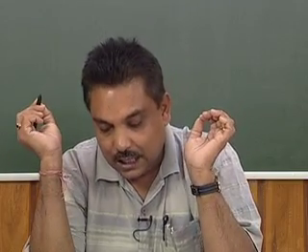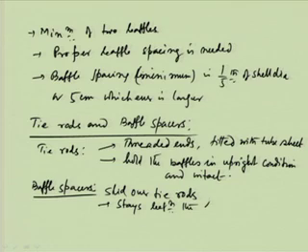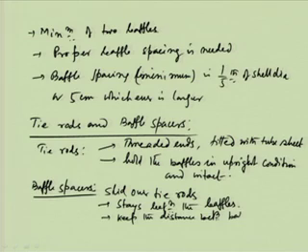These are hollow tubes which are slid over the tie rods, and they stay between the baffles, so that they maintain the distance between two baffles and keep the baffles intact.